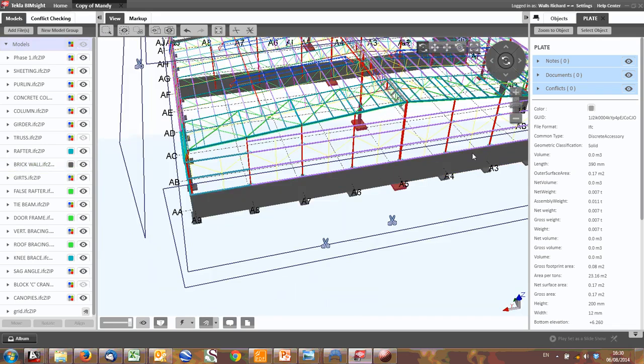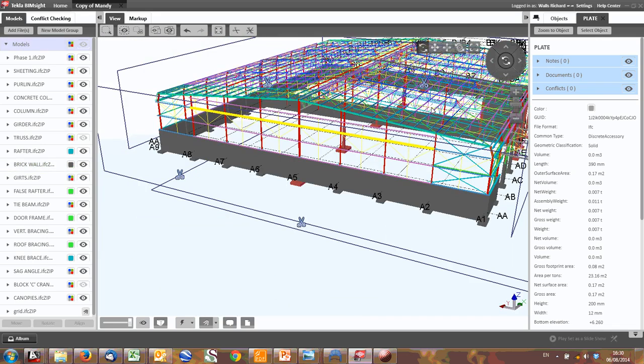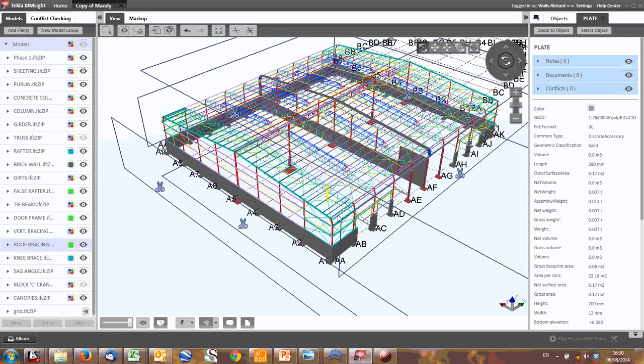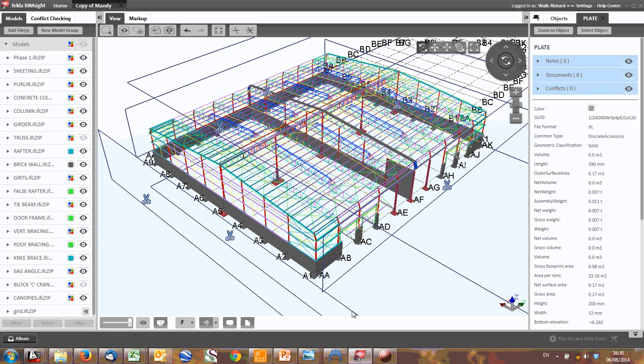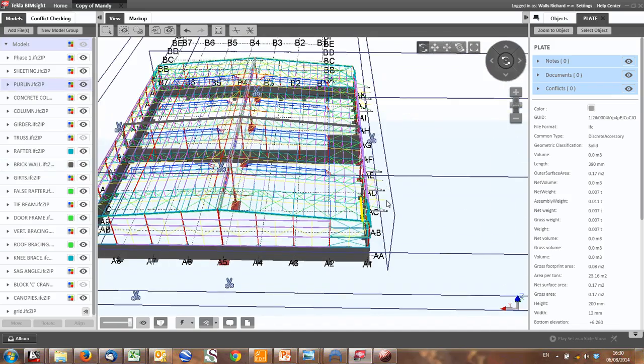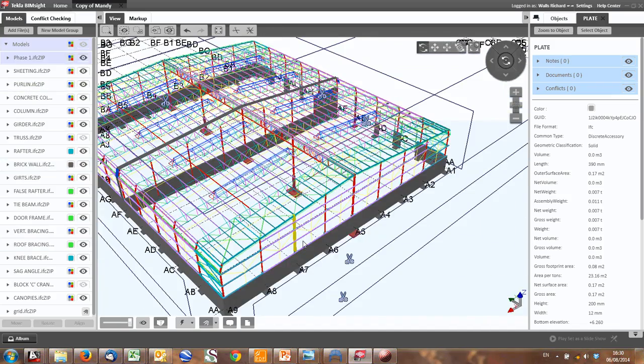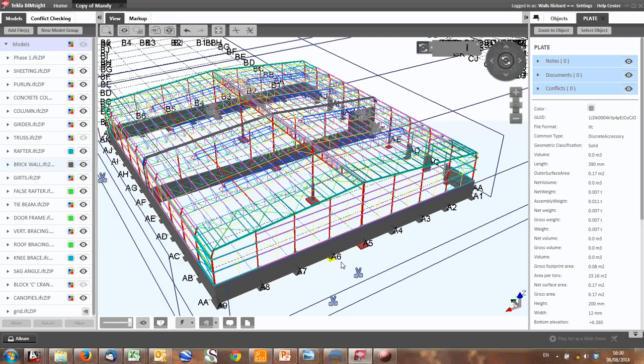For South Africa, we're not really looking at snow loads or earthquake loads. But this is quite a complex structure you're looking at. If you wanted to put that in a 3D model, you can just imagine modeling all of this. It would take a lot of time, a lot of effort, and also you add in things that might not be 100% modeled, and it will add stiffness where on site there may not necessarily be that same stiffness. So you've got to be very careful in producing a 3D model. It's not out of the question, but just be careful, be warned.